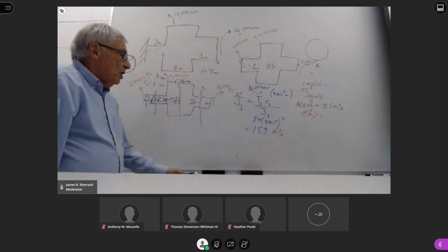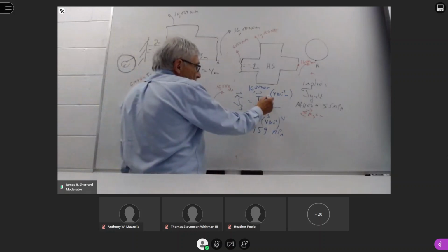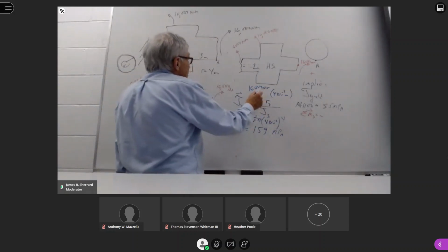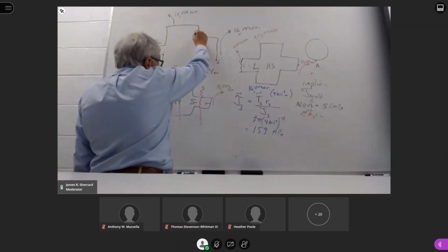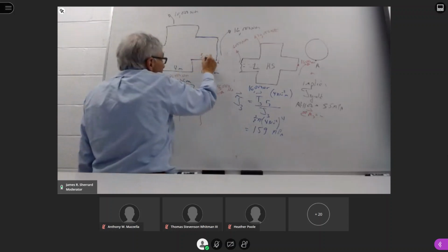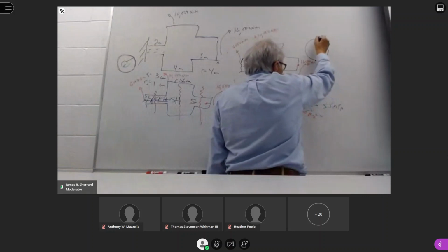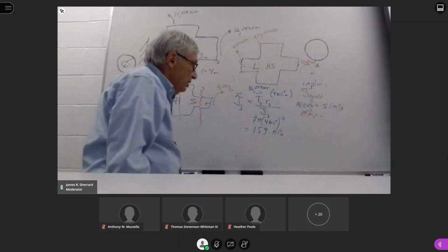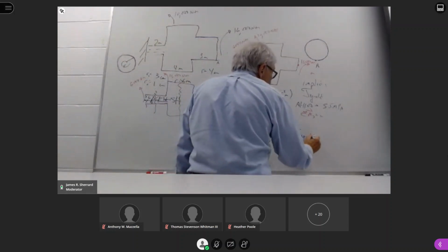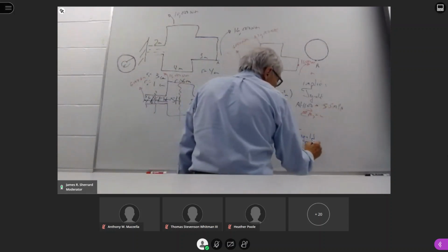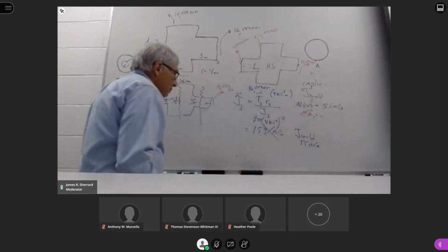159 megapascals. So I know this is going to occur because this is the maximum value of R. This is the torque that exists in the region. So we know in this region that value would occur first on the circumference as you see it here. This we're going to compare to the yield value, which again is 55 megapascals. This is greater than this, so it will fail.